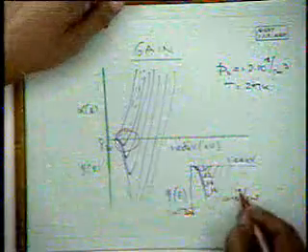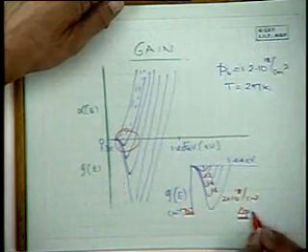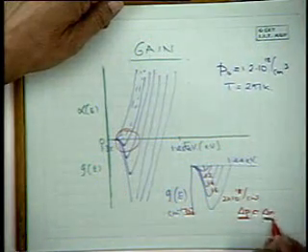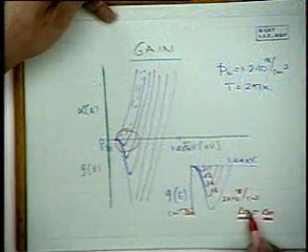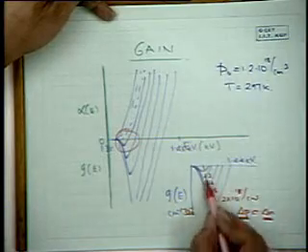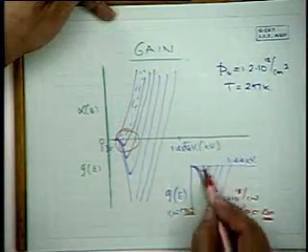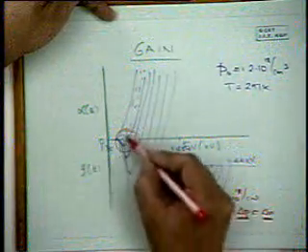This is delta P, and delta P is equal to delta N. So the Fermi level splits, and this excess delta P and delta N is obviously due to current J. The gain increases, and if the gain is enough to overcome the losses.